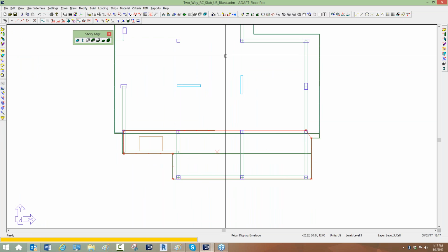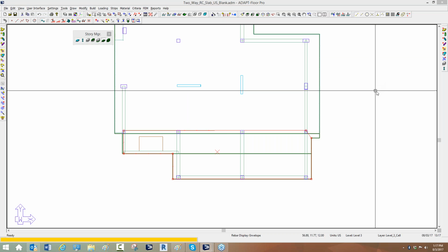The loading on the slab is always additive in the program. It never displaces the previous load. So in this case, in the region shown here, and I'll use my highlighter to outline this, this is 100 pounds per square foot because I get the 50 plus the 50 that's assigned here. If I would have made this input negative 50, which you can do, you can input a negative load, the loading here would have been 0. So there are ways to play with loads to try to reduce load or increase load depending on the overlap.